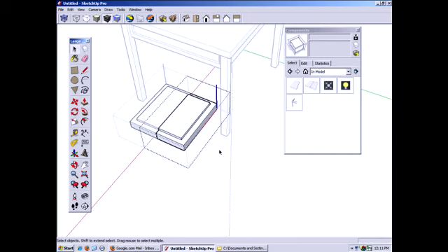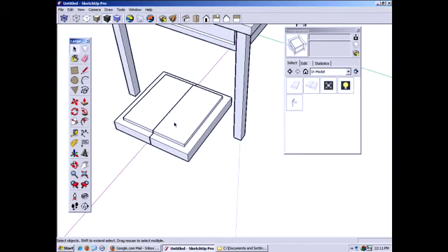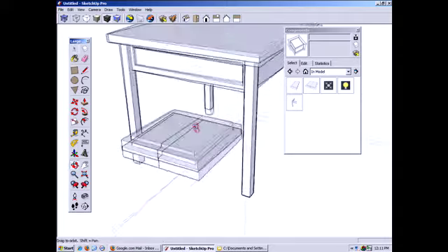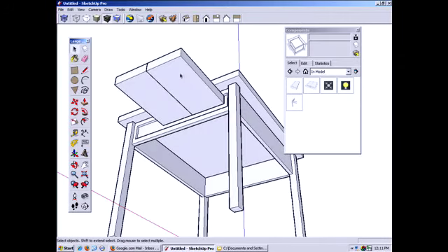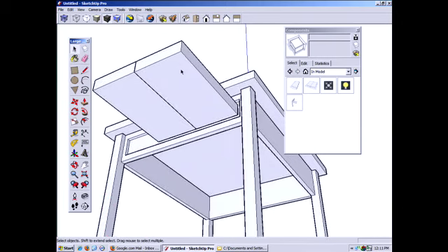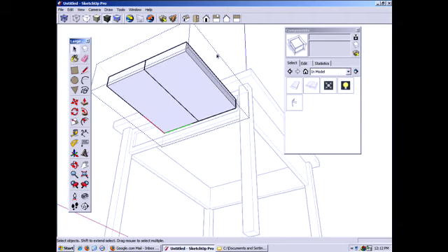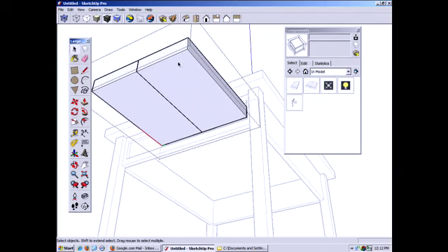You say, okay, that's well and fine. Well, why did you nest them together in the first place? Here's one example. Again, with the seat and the leg, before we had to copy it three times and move them out. This time, I'm going to come in and edit this at one level. Now, if I drew this rectangle and I were actually editing the seat, I'd get this on both sides.